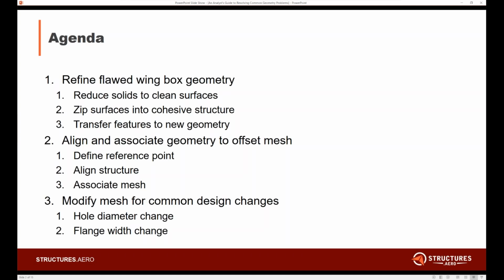And then we're also going to talk about alignment. I know with a lot of big projects, you sometimes get multiple coordinate systems going on, and a designer might send you a part that's part of a complex system, but it's in its own coordinate system. So when you bring it into your large analysis model, your FEM, it'll be in the wrong place. It'll be oriented any number of degrees off of where it needs to be. So there are some tools that can help you do that, and we're going to be using Femap-specific tools for those.